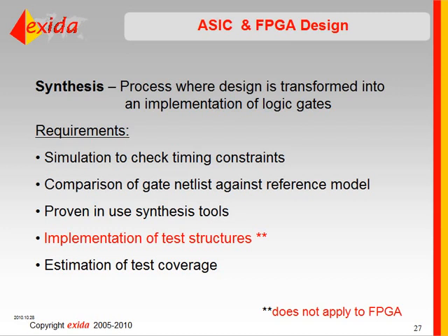All right, the next phase is synthesis. It's the process where the design is transformed into an implementation of logic gates. The requirement is you must do simulation to check that the timing constraints are met once the synthesis has been done. You must do a comparison of the gate netlist generated by the synthesis to the reference model, which is the VHDL code. And so essentially there are tools that will do this type of checking for you. The tools, once again, the synthesis tools must be proven in use. Use tools that you're familiar with and know work.